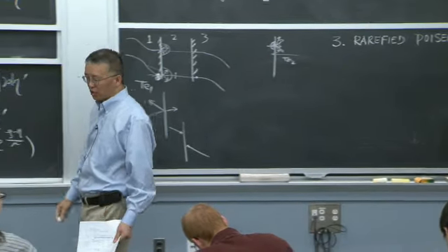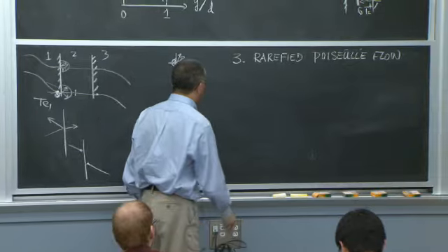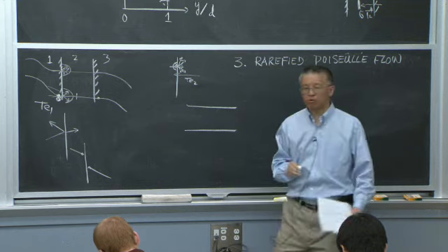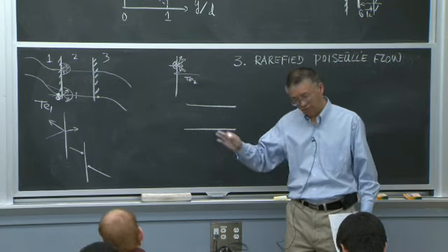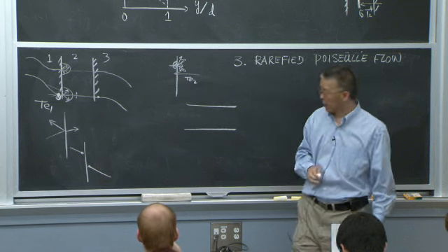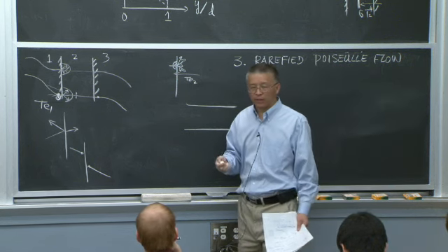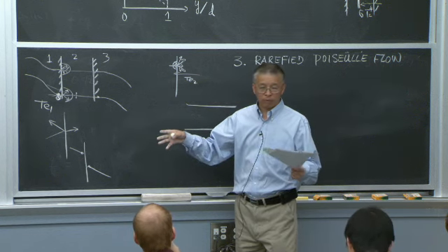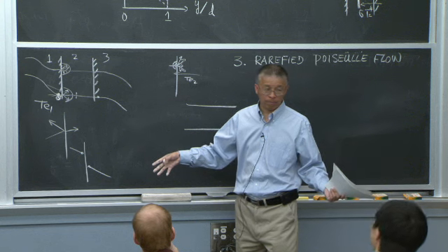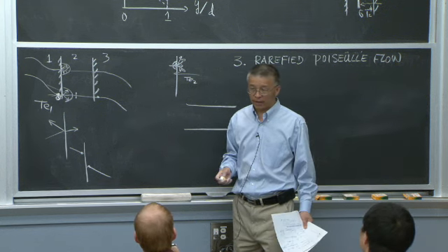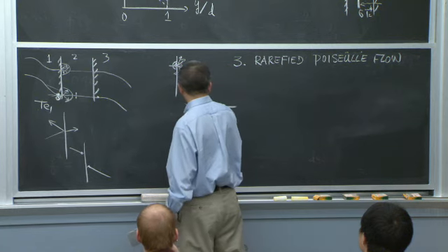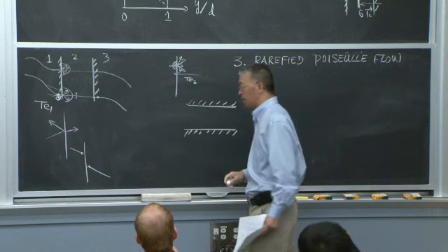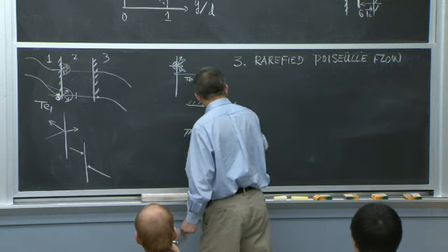Okay, so this is the pipe flow that you are all familiar with, but in the limit of Poiseuille flow, I say two parallel plates. Between two parallel plates, I'm flowing fluids through. And if one plate is moving and the other plate is stationary, that's Couette flow. If it's pressure driven, both plates are stationary, that's Poiseuille flow, right? You learned that in fluid mechanics. So I'm going to deal with the case where I have stationary plates and a fluid flow inside.